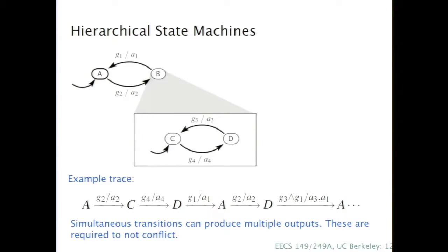So, for example, if I do a set action here, and I have a guard that depends on that variable up there, the guard will be evaluated with the old value of the variable, not the new. Okay? That turns out to be an important requirement, but for very, very subtle reasons that are a little bit beyond the scope of this course, but we'll hint at them when we look at feedback compositions of state machines, okay? Because it's a way of ensuring deterministic behavior of feedback compositions. But excellent question. Are there any more questions?